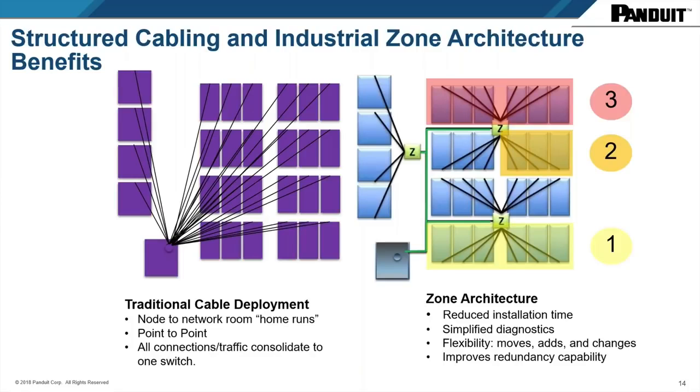That means that you would need to run 6 cables from area 3 back to the center in a star architecture, as you see on the left-hand side. And this type of cable will have to be a level 3 rated cable. So you have 1, 2, 3, 4, 5, 6 level 3 rated cables in all of its M.I.C.E rating that have to be run the length to get to the central system. That is a very inefficient way of running a cable because that is an expensive cable to start with. And then secondly, it's going to be running for a good long distance.